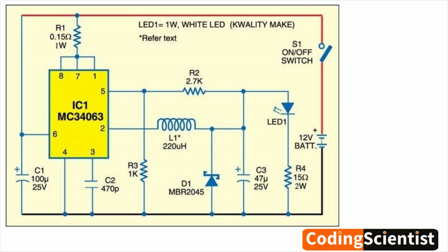The device consists of an internal temperature-compensated reference, a comparator, a controlled duty cycle oscillator with an active current limit circuit, a driver, and a high current output switch. These functions are contained in an 8-pin dual inline package. Another major advantage of the switching regulator is that it allows increased application flexibility of the output voltage.